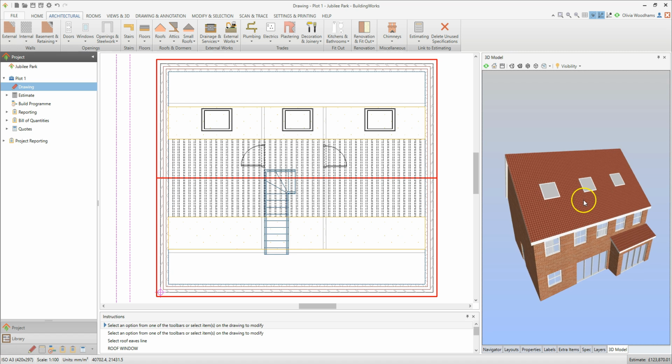So that's your introduction to drawing an attic in a new build property. Start by copying the first floor level to create your attic level with the wall height set to 0. Then draw the attic roof, taking care to select an attic roof type from the Roofs drop-down menu. Next, draw the attic components, starting with the upstands, then the attic floor, followed by the coloured ceiling. Add any partition walls and doors you need, and finally add roof windows to your design.